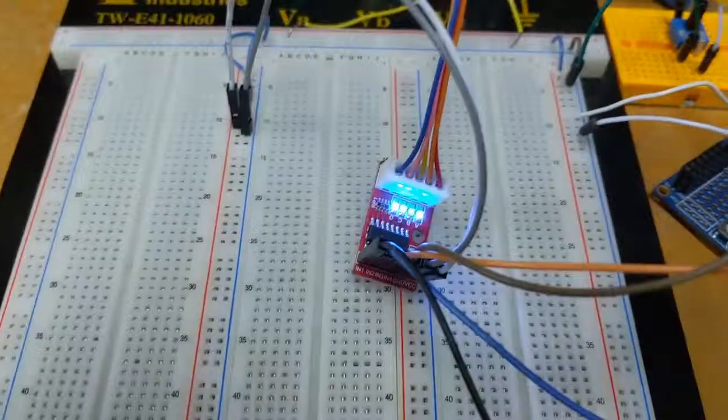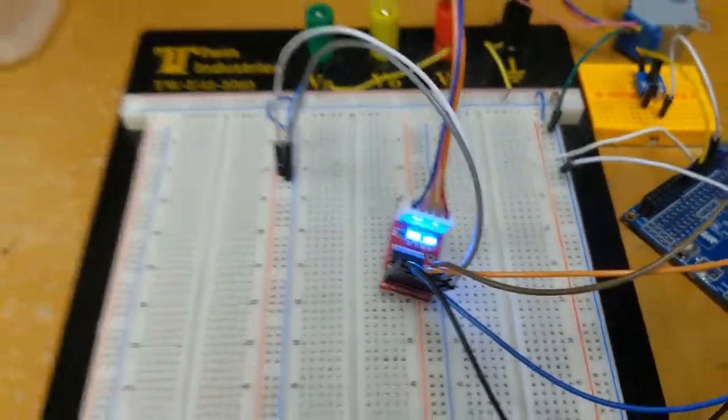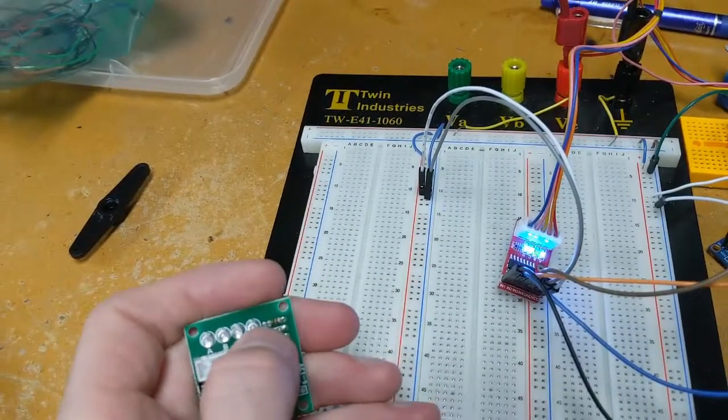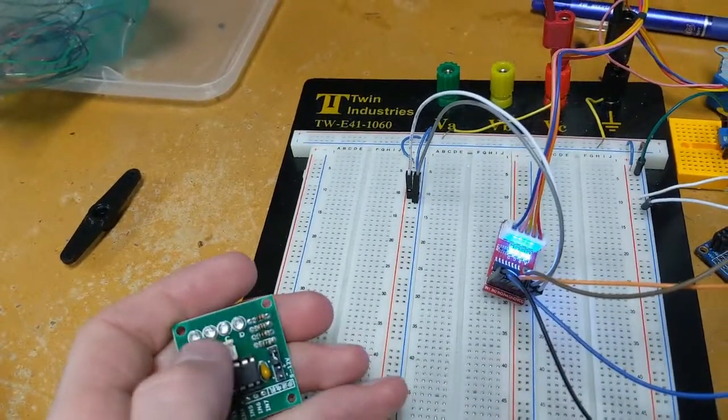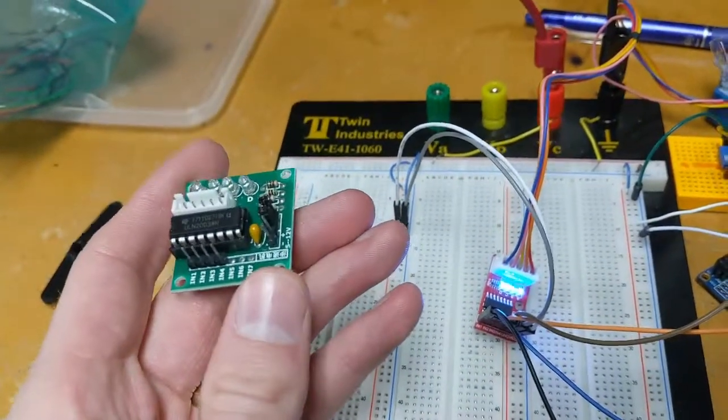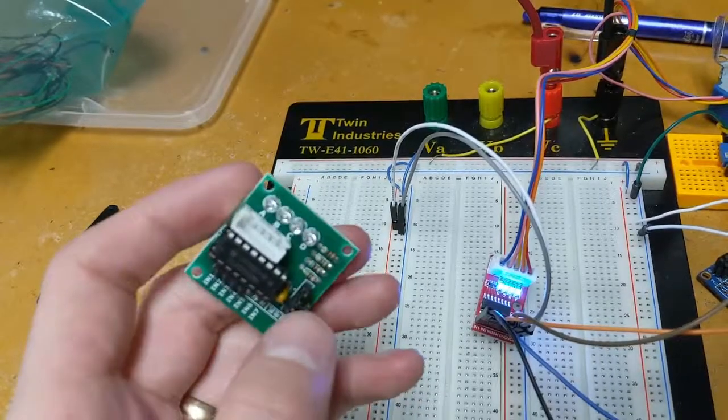This is the motor driver. I actually obtained some from somebody else, because the one I had was broken. Pin D was not operating correctly, so you only had 3 of the poles operating instead of 4, and your motor won't move. Maybe slowly, you might get some small iteration, but it wasn't enough.